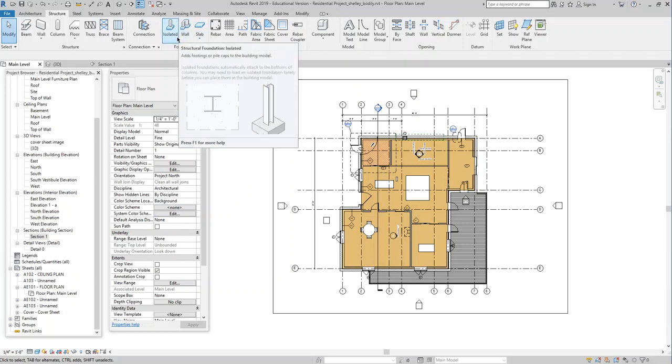We talked about with other elements in Revit how we have elements that are architectural and created for design intent, and then we have elements that are considered structural, right? I compared it to layers in AutoCAD, where structural elements are like structural layers, where a structural engineer will use those tools and that person will be responsible for them, right? Using these structure tools sort of designates them to the structural engineer.